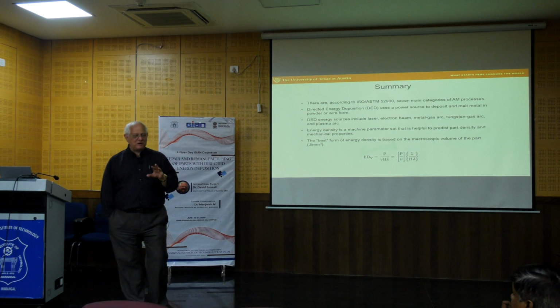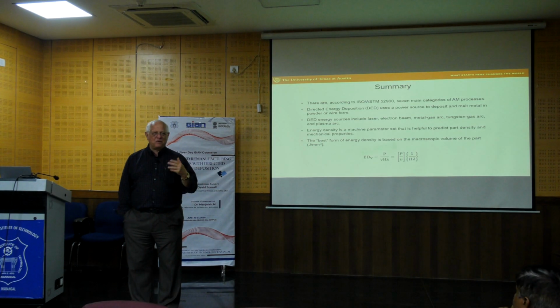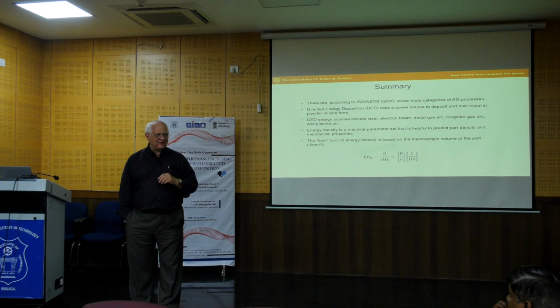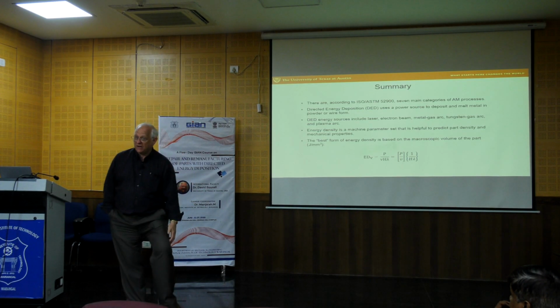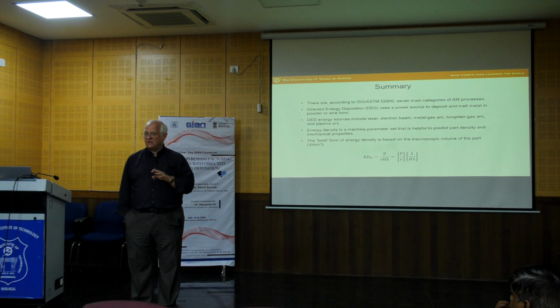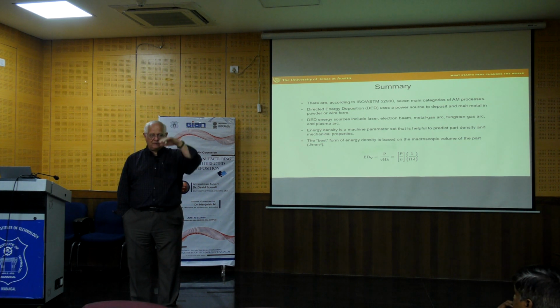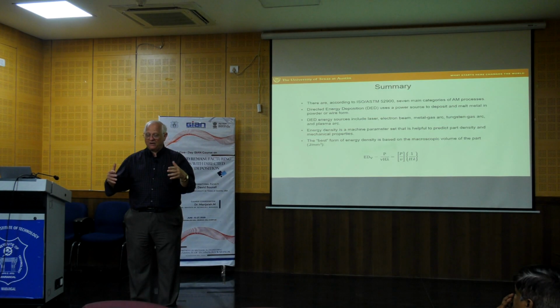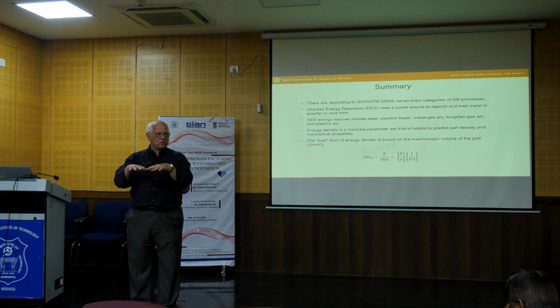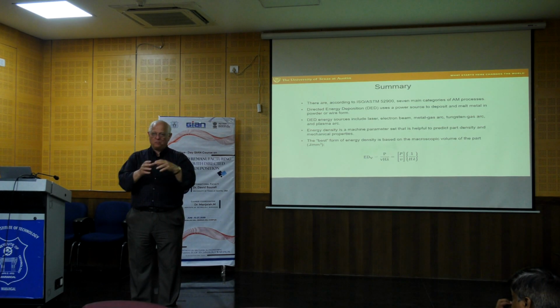My own personal opinion is, I don't know if they did a business deal or if they just stole the technology, but Neil Hopkinson in the UK had this technology that he called selective high-speed sintering, where he put down basically a coupling binder like carbon black, which can happen very quickly in the layer, and then he simply immersed it with an IR heat source, and where the IR heat source would see the carbon black it would get really hot, but where there was no carbon black, the material would stay relatively cool.